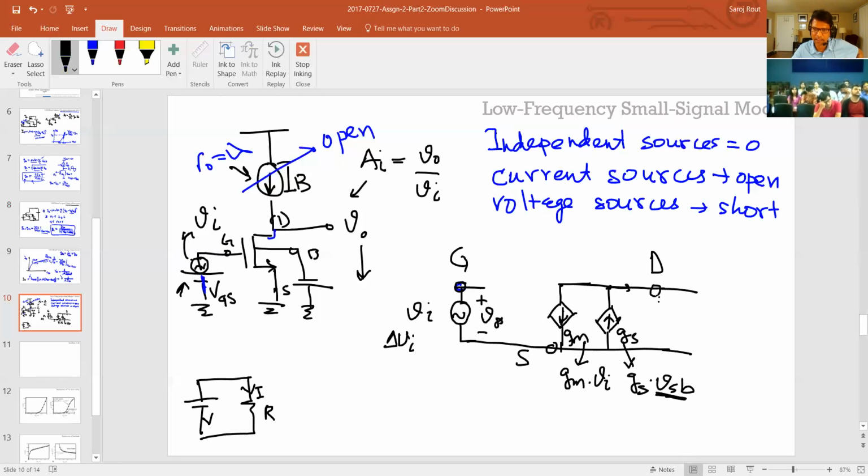And the last small signal parameter which you should have in this model is your output impedance, which is from drain to source, which is RDS. A lot of times we just write R0, right? So that's your complete low frequency small signal model for a MOS transistor. Now, as I said, most of the time this bulk to source is shorted, which means VSB equals 0, which means that this term is also 0, right? So all you get is this GM and RDS term.